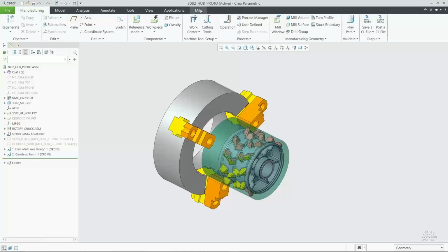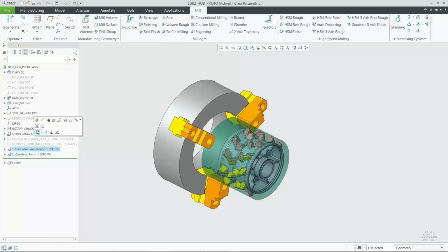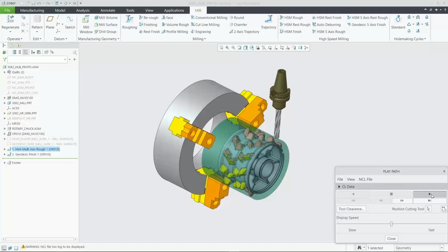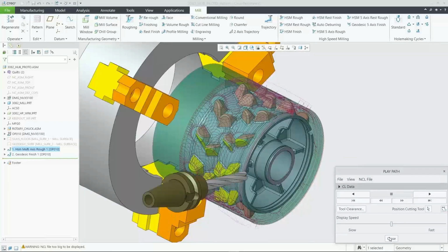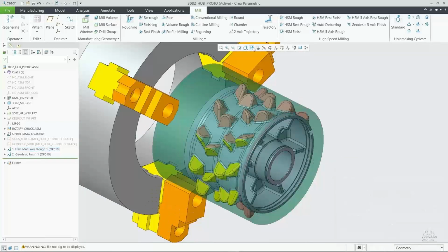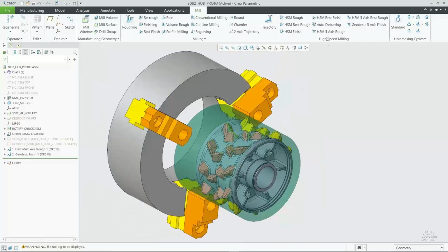And this is really what you want on a part like this. You don't want to spend a ton of time treating this like a 3-axis mill, which could take hours to set up. Just say, hey, I want to machine all of this. And since it's a multi-axis tool path, it'll rotate the tool for you automatically, gives you a very efficient tool path. And that was actually something that was introduced in Creo 8, but with Creo 9, we have a new one. Somewhat related, but this is now the geodesic option.